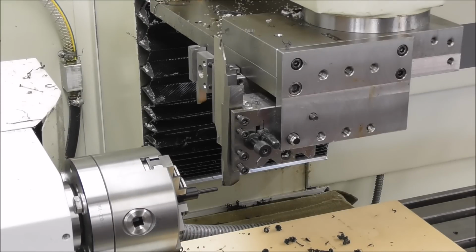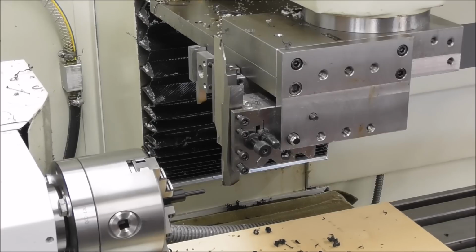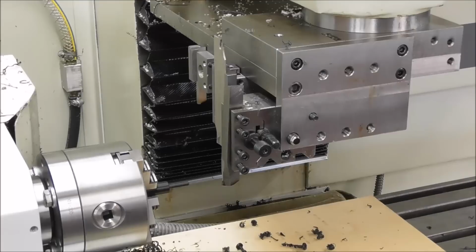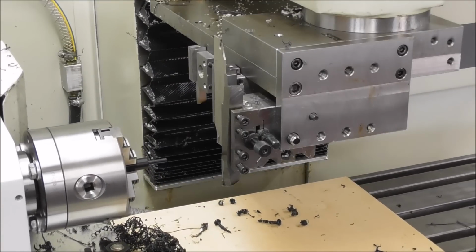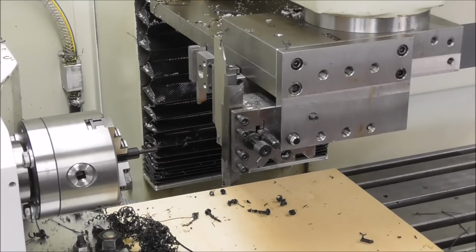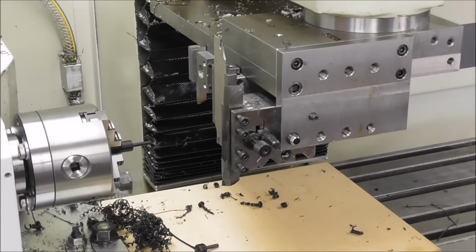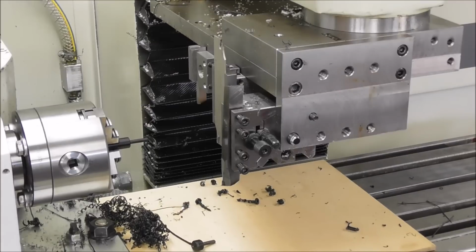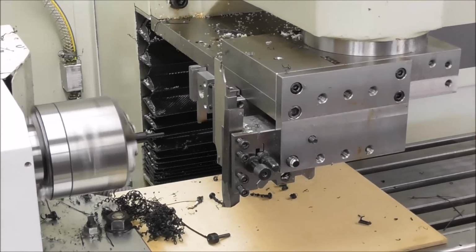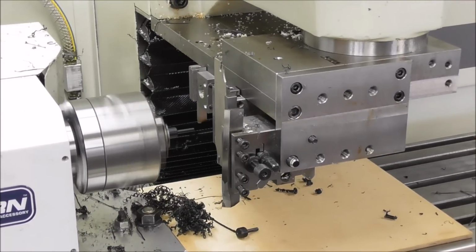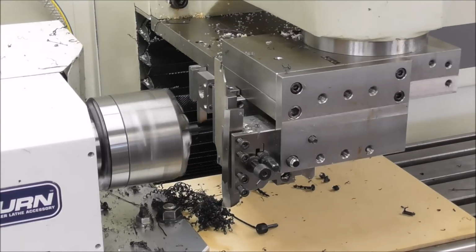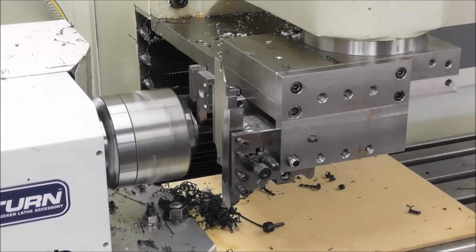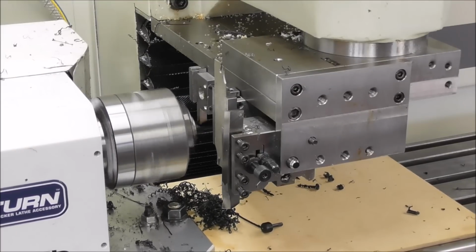So we've just slid the maximum velocity slider, that's the bottom slider, right down to 0. And we're just going to creep it along, making sure everything's clear. We've backed off in our G30 position and we're looking to check nothing's going to foul, everything's okay. Looks alright. And you can just slow right down. At this point, you're going to do the threading operation, and it's really slow. That seems okay.